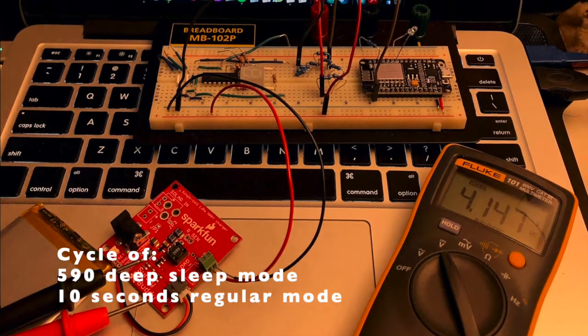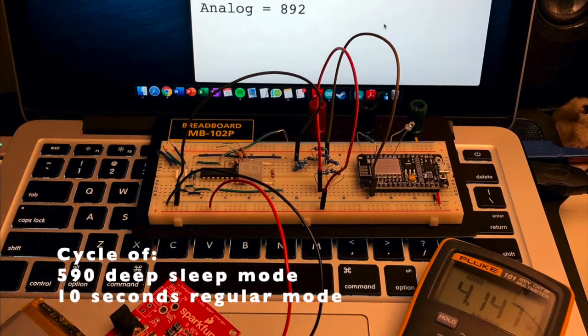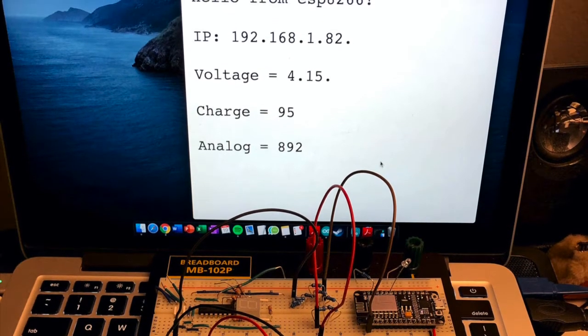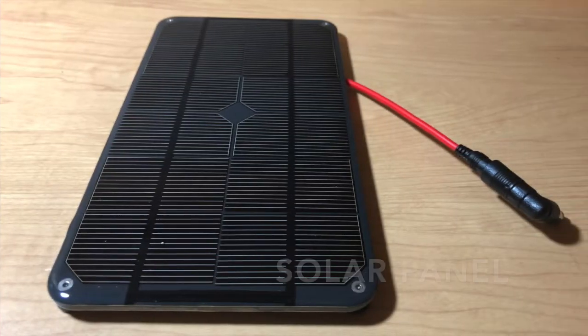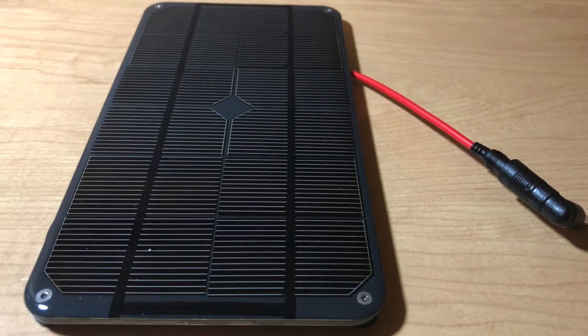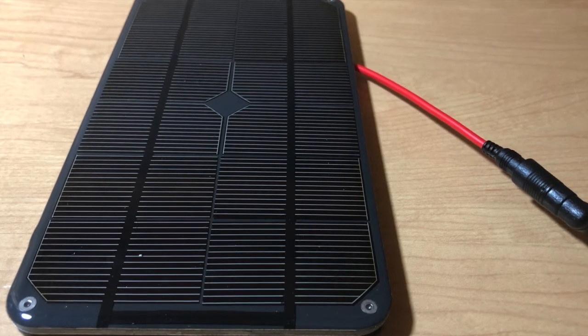It is determined this is enough time for the microcontroller to reconnect to the server, measure data, and enter Deep Sleep Mode again. Through estimations, a 2500 mAh battery will, therefore, be able to power the device for around 60 days. With a conservative estimate of 4 hours daily sunlight and 60% efficiency, the solar panel will generate 8.4 watt-hours per day and 1.2 amp-hours per day.